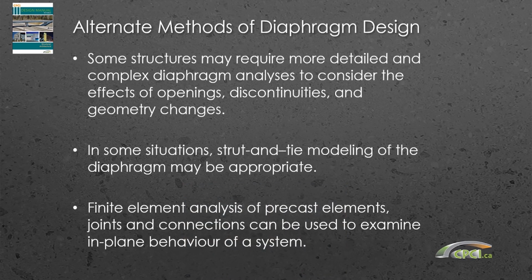So some structures may require more detailed and complex diaphragm analysis than others. You should consider openings, discontinuities, and geometry changes. So really the simple beam analogy may not always apply. In some situations, strut and tie modeling may be more appropriate.